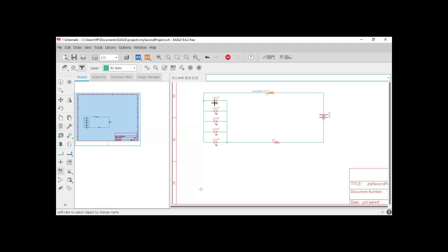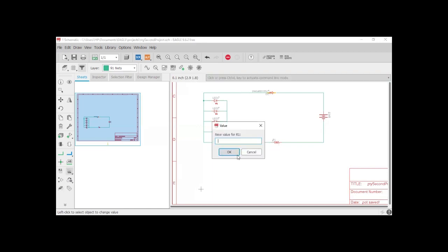So the next thing is to rename. We need to rename this diode because here we're having D5, which is not D5. I'm going to change it to D1. So the resistor is there, the battery is there, B1. So the next thing is to add values to any component that needs to be formatted with a value, like this resistor. We're making use of a 10K resistor.